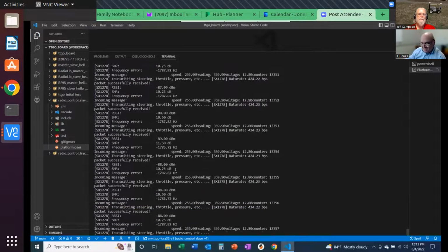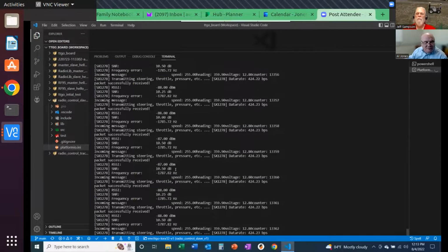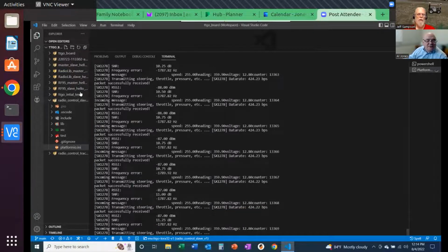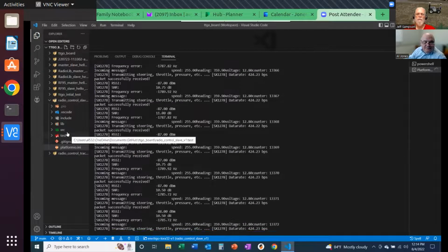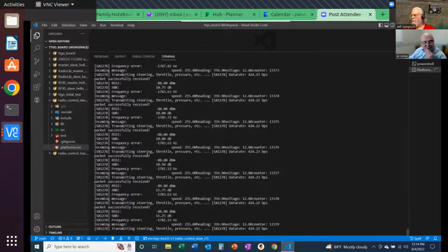would receive the heading and speed, and I haven't added it to the structure yet, but I also think receiving back the RPM would be useful if you get that Hall effect sensor working. I'll have to do something similar to get the Hall effect sensor working. So this Windows 10 machine is also running Visual Studio Code, and that's just, I'm switching to that as the IDE, and PlatformIO is the extension that's useful to upload the programs to the TTGO boards.